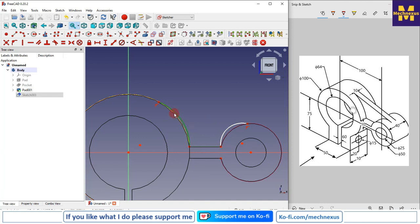Now I will select this arc and my projected arc and make it equal. Similarly here I will select both the arcs and make them equal, and now I will draw a line to connect this. So here we will assume that this point is in a vertical relation with the center of the circle. So I will select these 2 points and add the vertical relation,